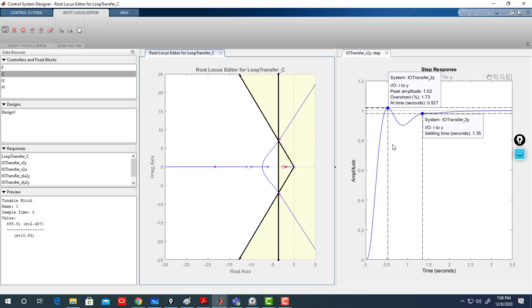If you want to go deeper and study more, you can look at the control effort signal, and you will see that if you don't allow overshoot, you may have a high control effort. So it's better to allow overshoot in your design. It depends on the system itself whether this is acceptable, or what your design requirement is as a control engineer. In this case, they asked me to have an overshoot of 20.